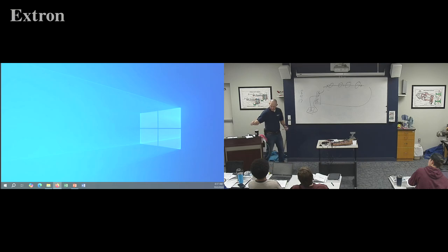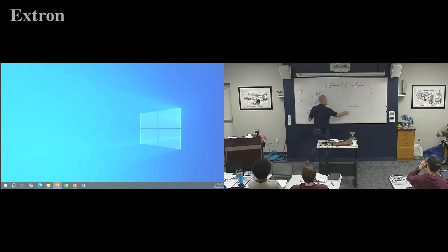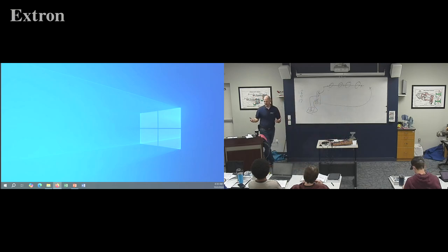And the last one, I think. Austin, if I go from here to here across my break, what do I get? Would that be 0? That one would be 12, because I've got my full negative coming to this point, and we just said we still have our full positive because we don't have any amp draw. So our little amps are all pressurized up. They're like, I want to go somewhere, but I can't get across the gap. So that would be 12 because we have the break in the line.